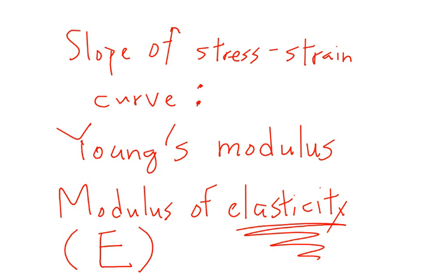That's the most general definition of elasticity: after you do something to this object, it returns to its original state. So in mechanics of materials, elasticity basically means if you apply a stress or apply a force to a part and it deforms, then after you release that force, it returns to its original shape.